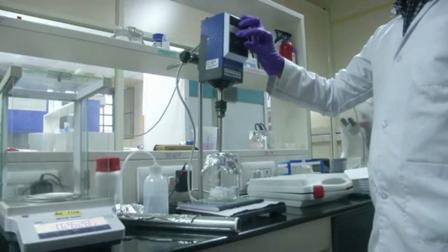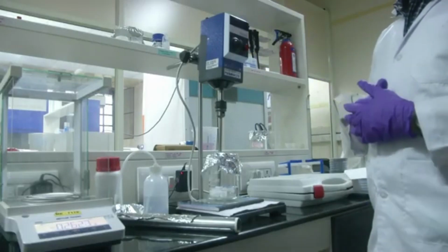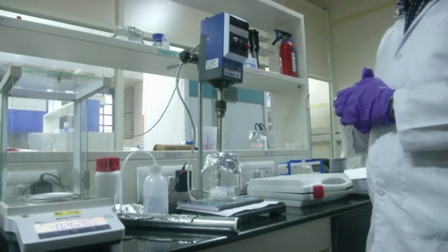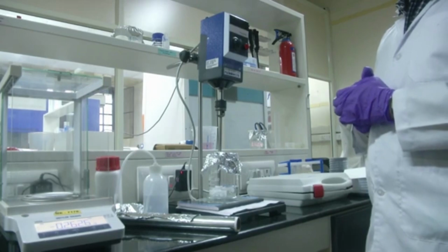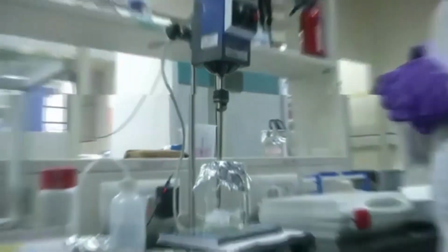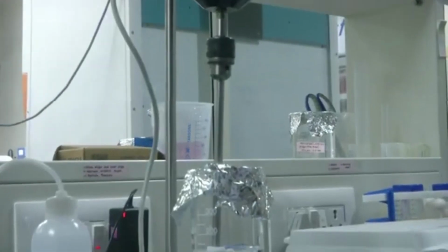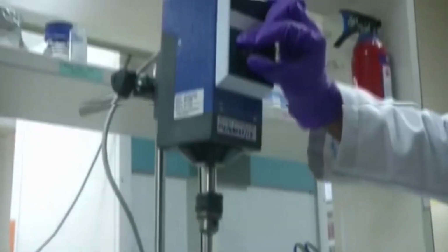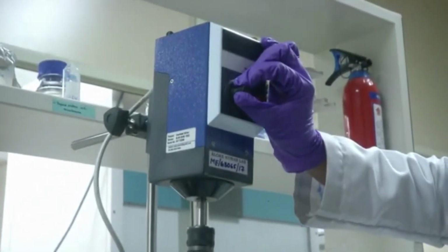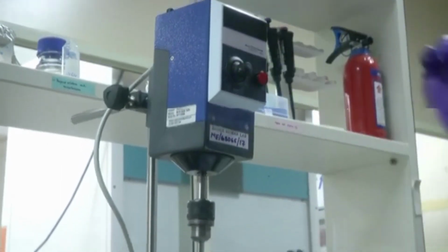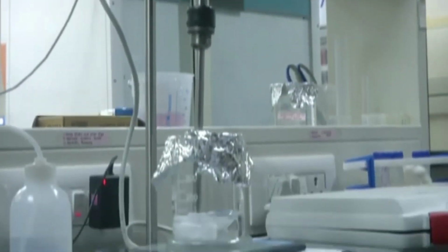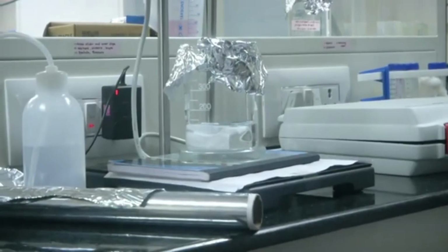Now coming back to the mechanical stirrer, it is useful to note that the mixing time is not fixed. It's not a fixed parameter. It depends on the solution that we are preparing and the method of mixing we are using. You can notice that using the mechanical stirrer, it only takes about 3 hours to prepare the solution, whereas the magnetic stirrer takes about 24 hours to prepare a uniform solution.